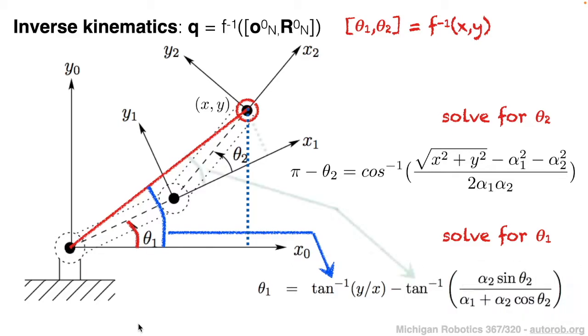And it turns out that we can do that also using inverse tangent and some additional trigonometric properties. So we have that calculation here. Once again, it's essentially using the same kind of idea where we're going to take inverse tangent based on the opposite component and then the adjacent component, which we're calculating here, and then the result of that is we have theta 1.